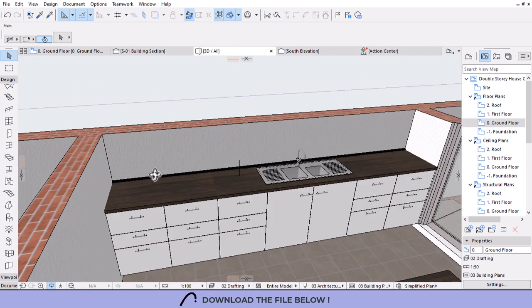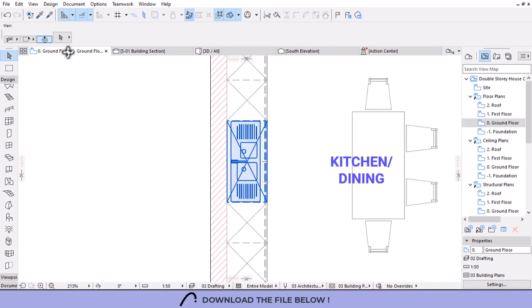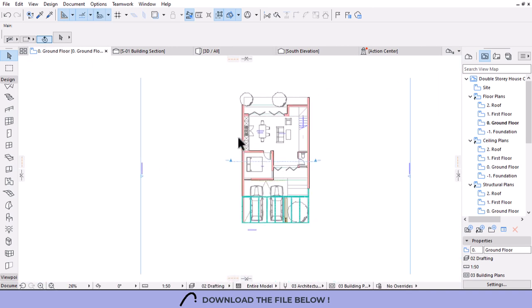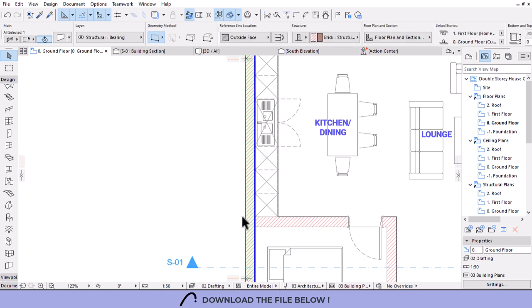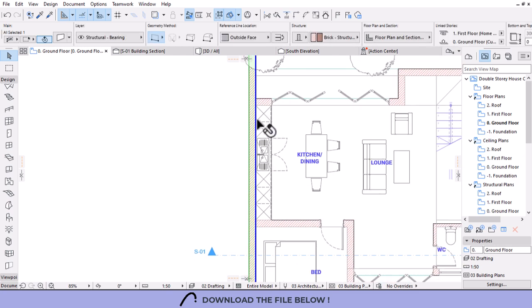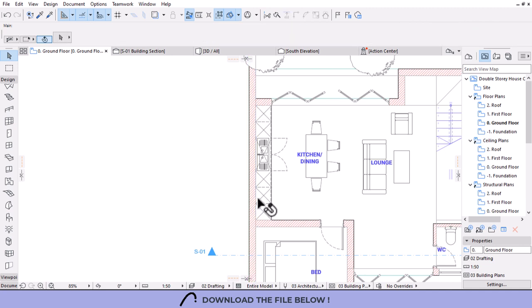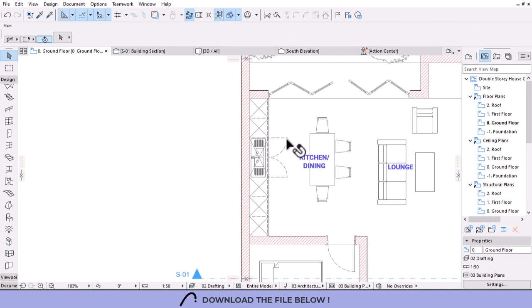But before we do the wall cabinets, we need to treat this wall and add a finish here. There are different ways of doing that. We can split this wall into two parts, split it here and then split it there, then we override the surface. But I don't want to increase the number of polygons for this project. It's very important to know how or to use best practice to manage your project file well. So instead of doing that, I would use a composite.